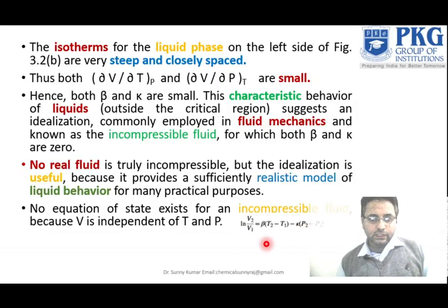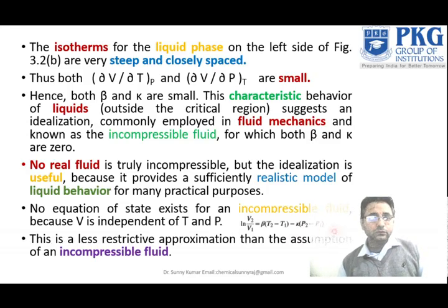If you integrate that one, ln of V2 upon V1, from state 1 to 2, you can get beta times (T2 minus T1) minus K times (P2 minus P1). This is a less restrictive approximation than the assumption of an incompressible fluid.